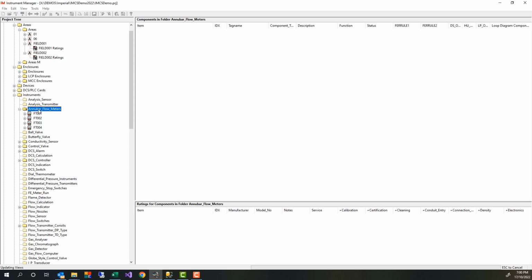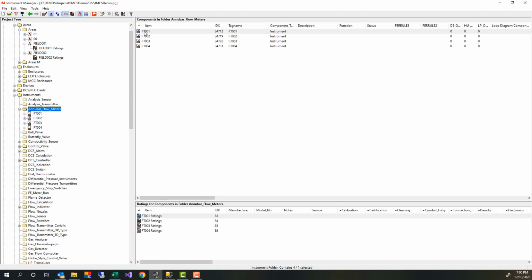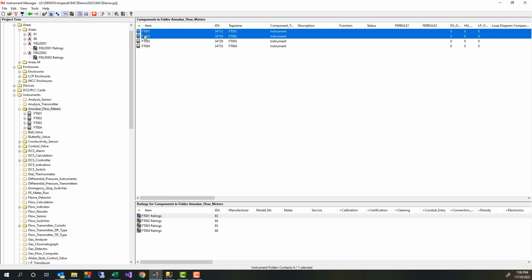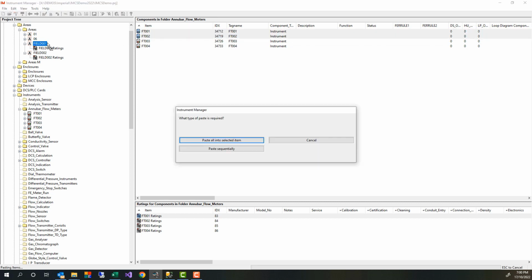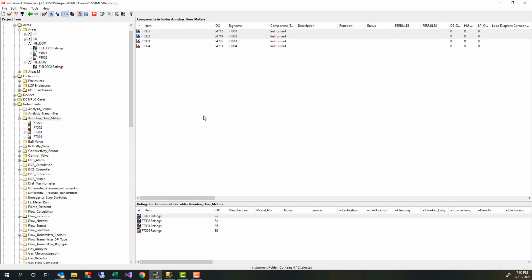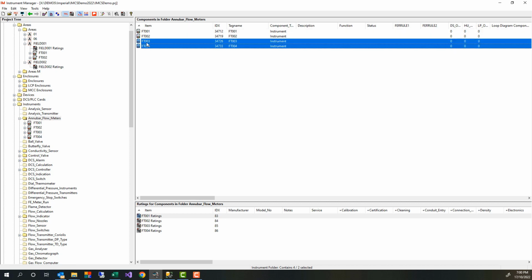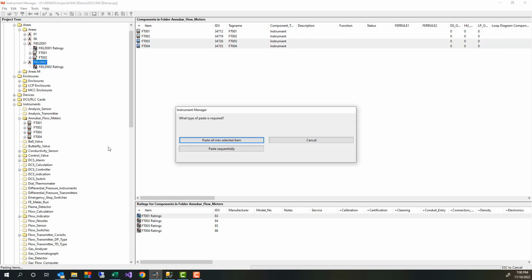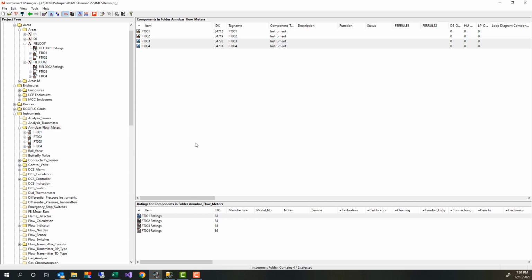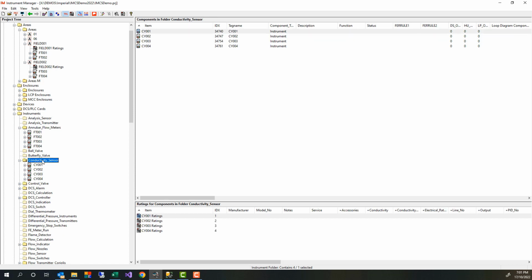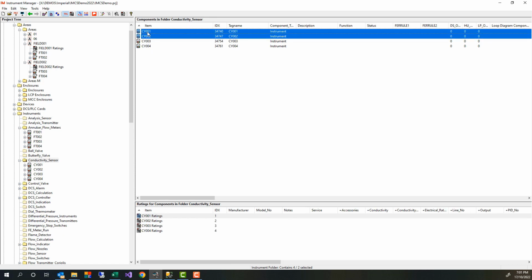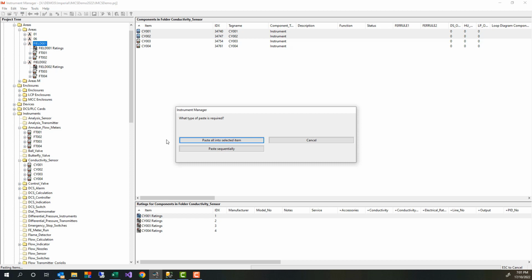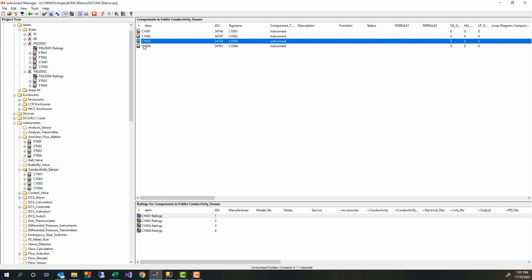On screen I have 2 areas displayed, Field 1 and Field 2. I will now parent 2 of my new flow transmitters in each area. Typically, we drag and drop components to make a database link. However, many components can be automatically contained or associated when importing data. Terminals and cores are automatically parented by terminal strips, devices and cables when those parent components are created.